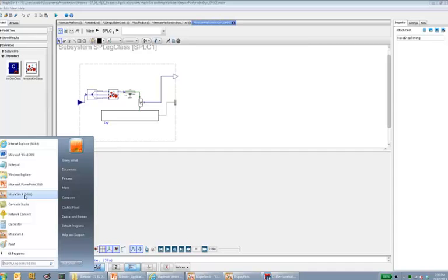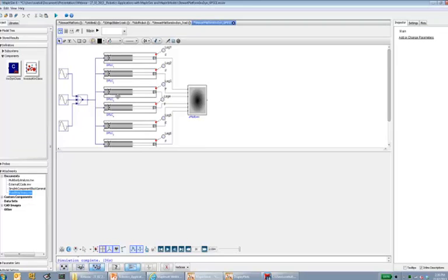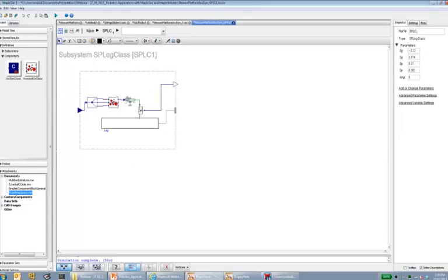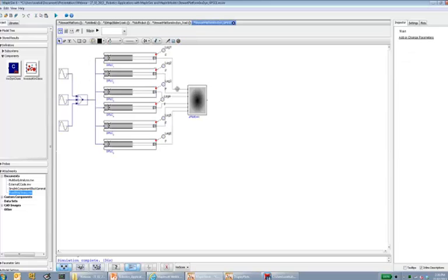Now we want to do better than that. Right now we have the inverse kinematic blocks, which we use to actuate each leg, and then use a force sensor to measure how much force is needed to move each leg according to the inverse kinematic solution, which gives us the forces, or inverse dynamic solution, of the Stewart platform. We want to know if we can do this calculation in a straightforward way without going through the multibody analysis.